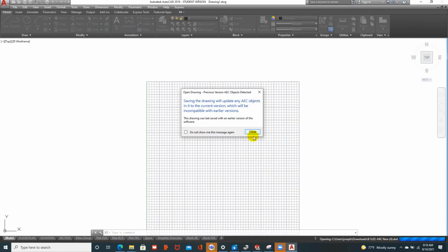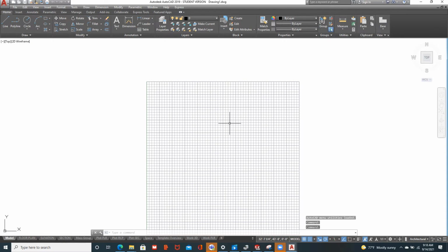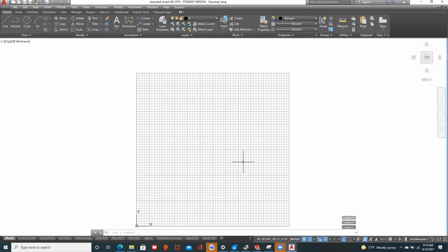So let's get started. We have this grid that's set up within the limits of the display, and that's because we're using grid display set to 0. So if I say grid display and it's set for 0, then the limits of the drawing will enclose the grid values.